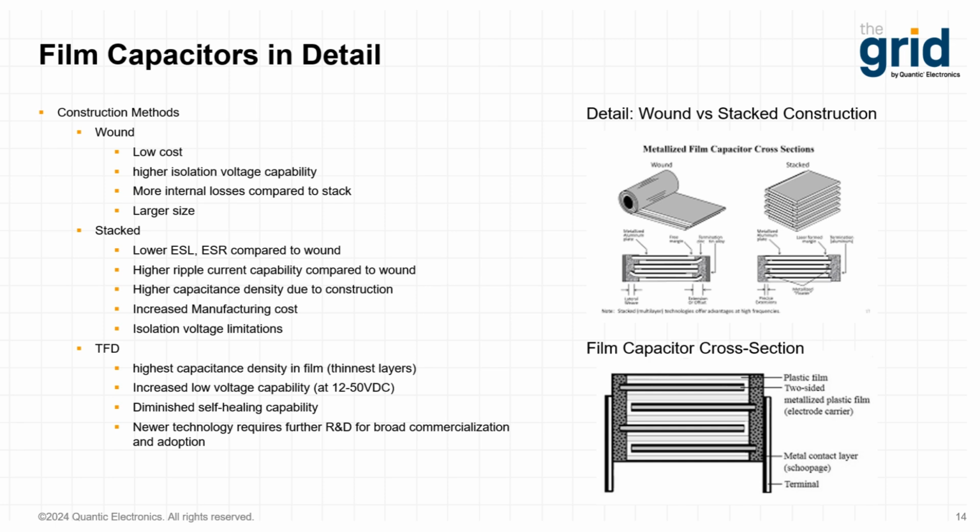Lastly, TFD, or thin film deposition. This technique consists of depositing layer upon layer of metal electrode followed by plastic dielectric on a large drum, resulting in a large capacitive element that is later cut up, stacked, and leaded.